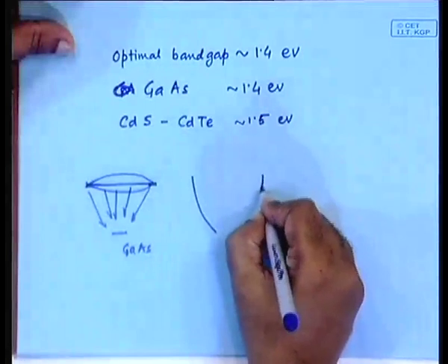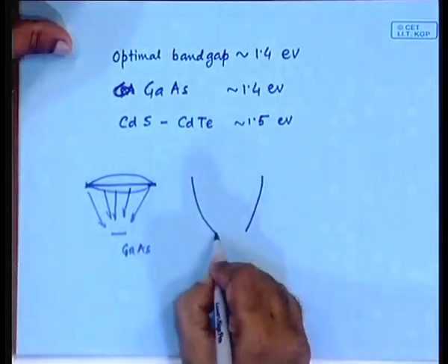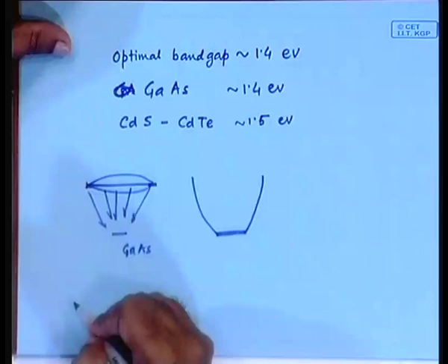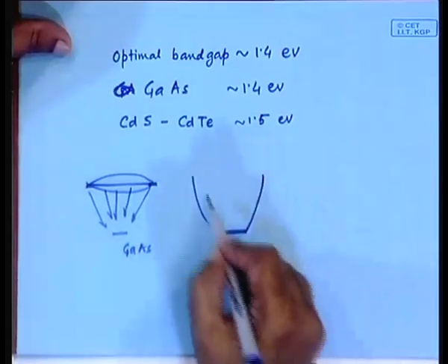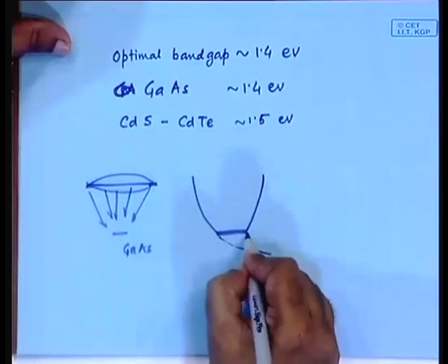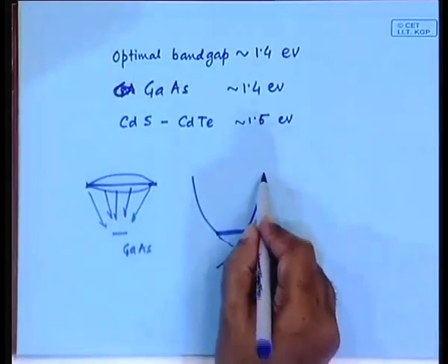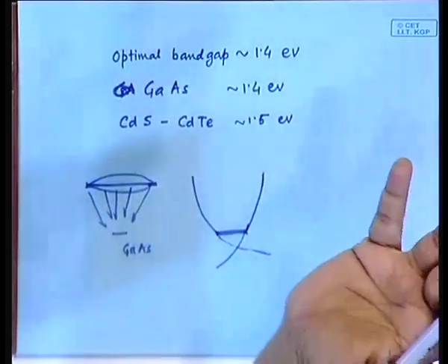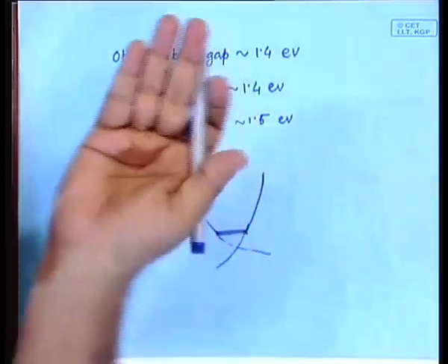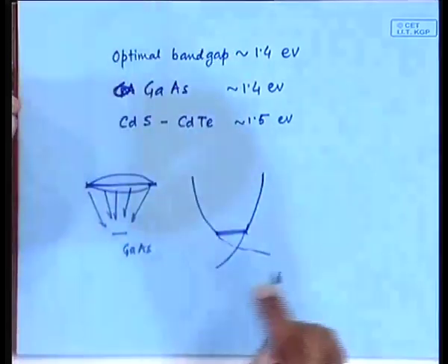The other type of concentrator that is considered is the reflecting concentrator, and you have learned what kind of reflecting concentrators. For example, the Winston's profile, where you have, and here is the gallium arsenide solar cell. These are two parabolas, and here this parabola has this as the focus and this parabola has this as the focus. That is the construction. So, you can have some kind of an aluminum reflecting bowl, and on the bottom of it you have the